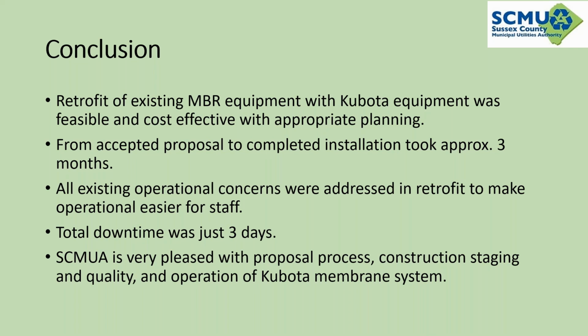I know I probably shouldn't have even said that, but we have done the necessary CIP in accordance with the training and the O&M manual, not out of necessity due to the TMP or the permeability, but because that's the recommended duration in the O&M manual.